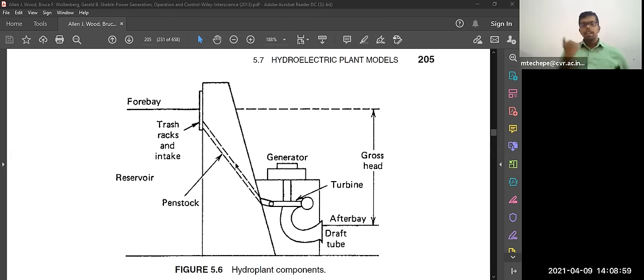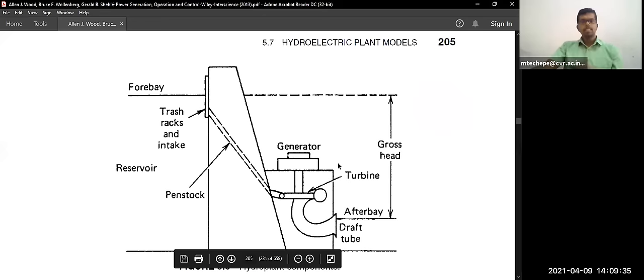So this turbine will not rotate at 1500 rpm like what you see in your machines lab. In that you'll be finding an alternator rotating at 1500 rpm, because it is coupled with a motor whose speed is 1500 rpm. So the generator also rotates at 1500 rpm. Whereas in this scenario, the speed of the turbine will be only 200 rpm.